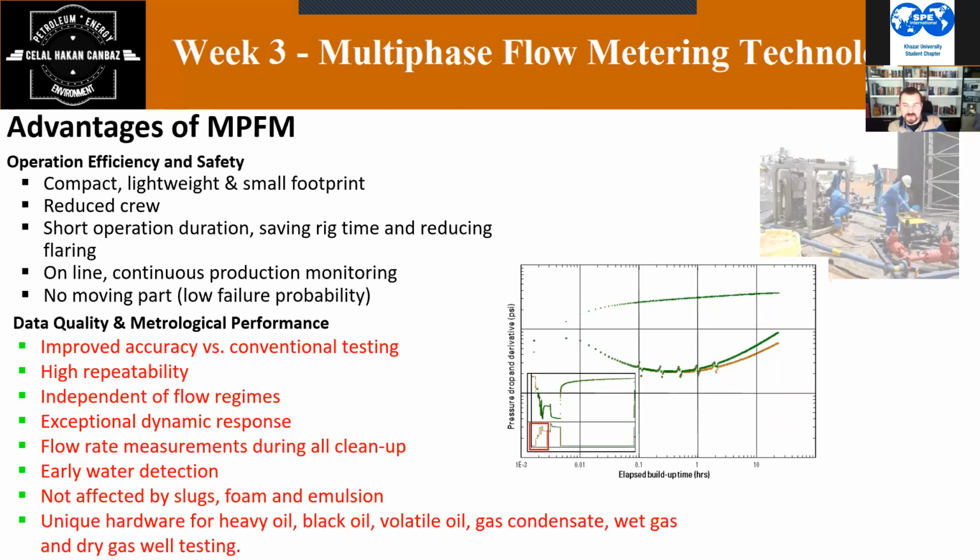So it's not affected by any of these because it's measuring in microscale, not a total measurement of flow. For example, if a foam comes, a slug comes, it just says that this molecule belongs to gas, this molecule belongs to oil, this molecule belongs to water. So because of that, it's totally independent from emulsions and foams, okay, and slugs also, of course.